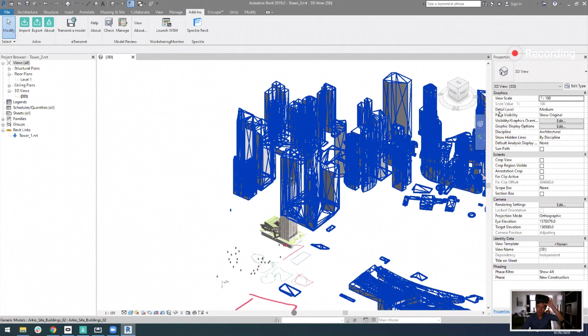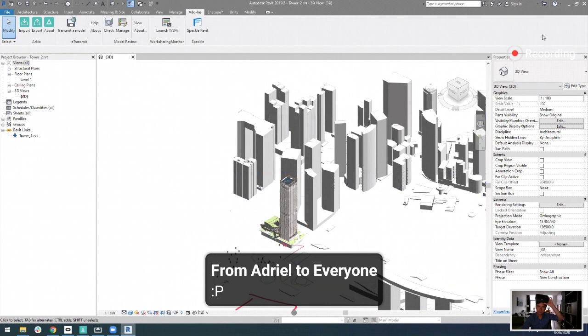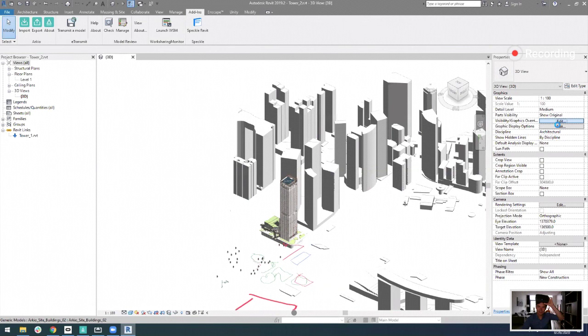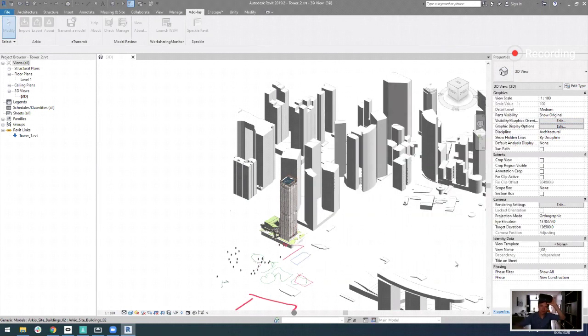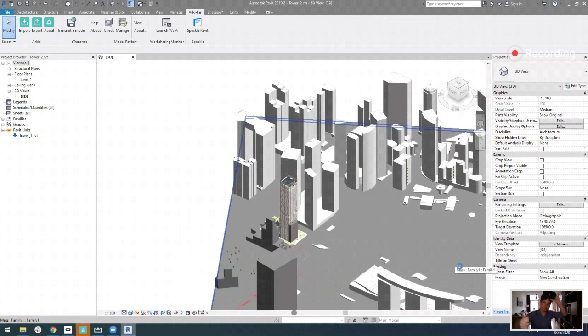So when you were pulling up some levels, you have set floor-to-floors for specific buildings, yeah? Yeah, so these slices that you saw appearing when I pulled the shape out of thin air, those are by default set to 3 meters, but you can define them specifically. And the height adjustment that I just did when I was stretching things, they allow you to make fine adjustments on some levels that need to be higher, for example.